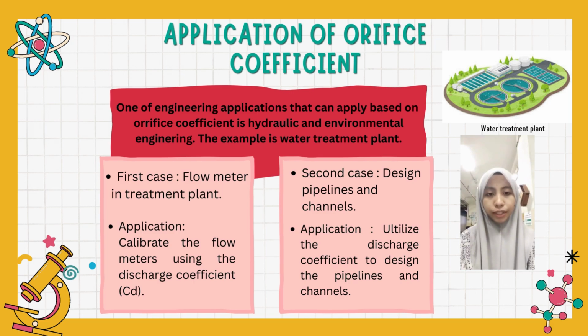One of the engineering applications based on the orifice coefficient is hydraulic and environmental engineering. The example is a water treatment plant. There are various components that can be used in this application. The first component is flow measurement and control. The case is flow meters in water treatment plants measure the flow rates of water and chemicals. The application is to calibrate the flow meters using the discharge coefficient, CD, obtained from the orifice coefficient experiment to ensure accurate flow measurements.